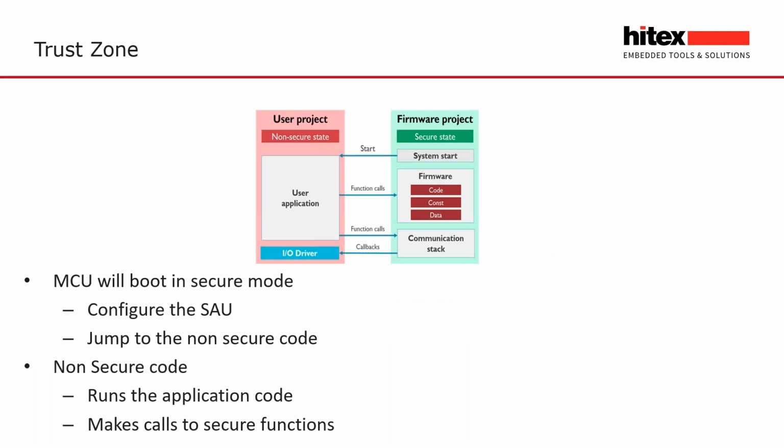So we've now got two projects. We've got the startup code that will partition the chip. Ultimately, we'll also have the memory protection code that will run with the operating system in real time. We can make calls across into the secure code, and we can also do context management for the operating system as well.